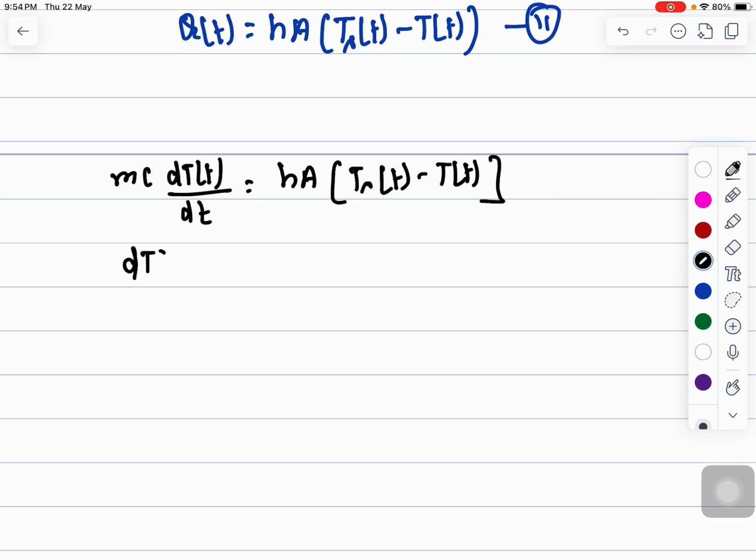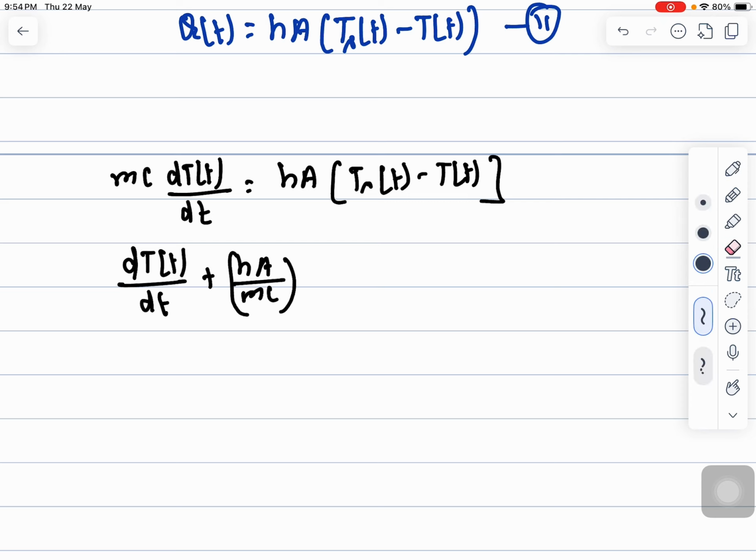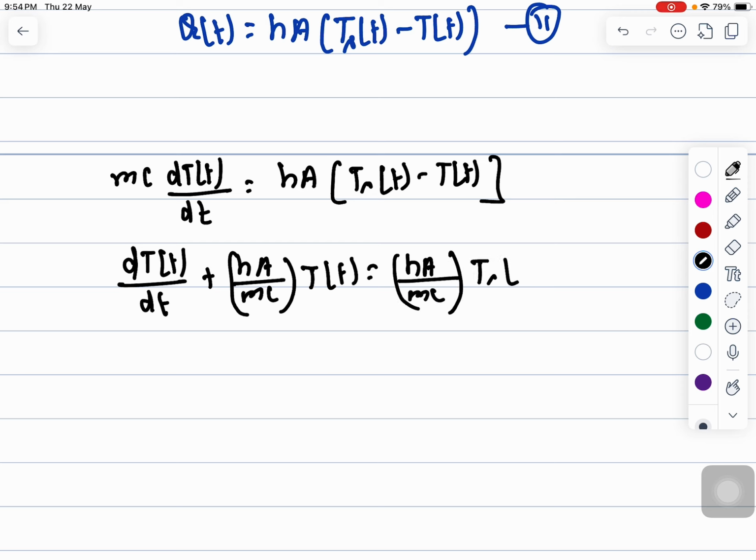So dT/dt plus hA/mc times T equals hA/mc times Ts(t), right?